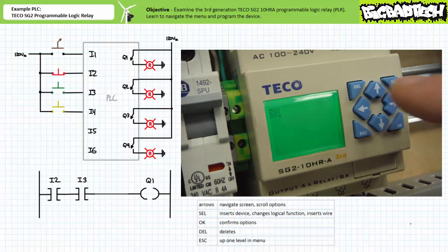Once you've got whatever contact function, right arrow to the contact number. We want input 2, so we're going to increment to 2. Press OK to confirm input 2. The device inserts input 2 as a make instruction and moves us one column to the right. If you dork something up, you can always delete it.